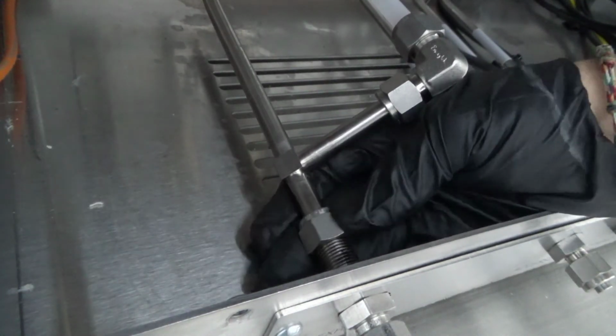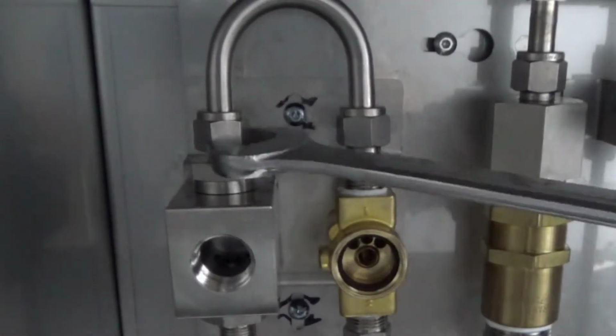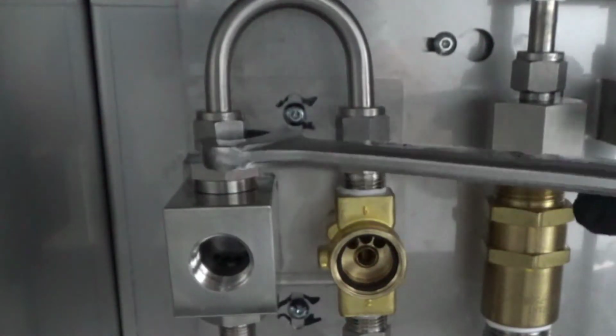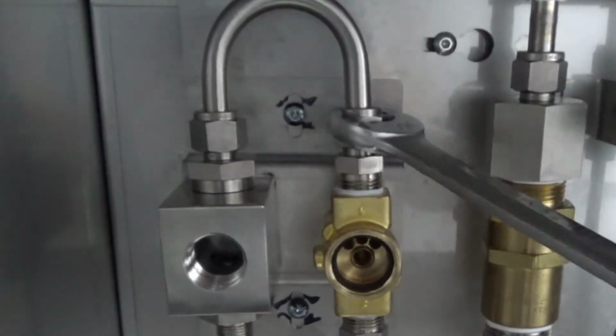We will simply reassemble in the reverse order, starting with the wide weldment. We will want to make sure we finger tight all connections first before we fully tighten any of the connections. All while using our proper swage lock tightening procedures. It is especially important while reinstalling the wide U-shaped pipe below the moisture sensor block and exhaust filter to finger tighten before using any tool to prevent the possibility of cross-threading this connection.